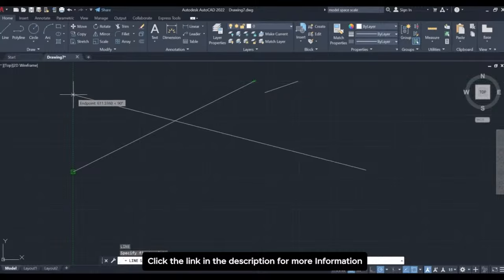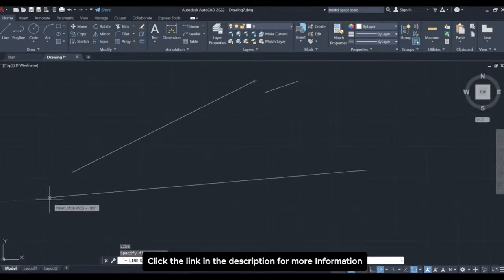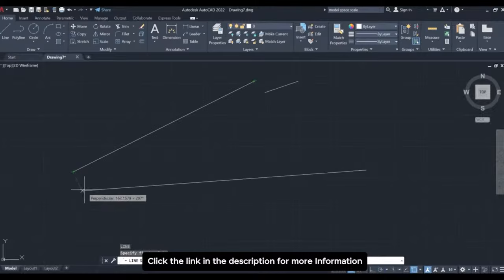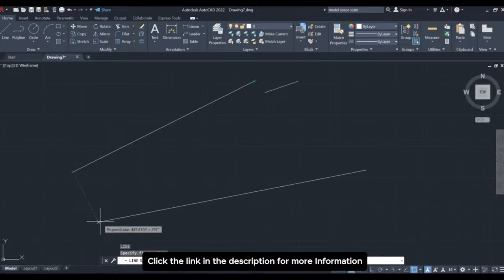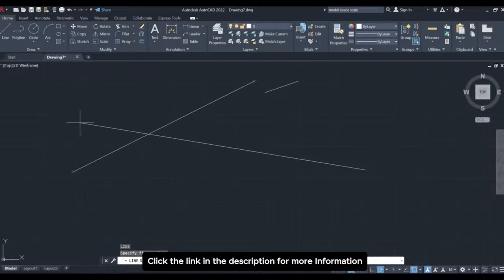All right. If you ever want to turn off this green line, which helps you track across the object snap, just press F11 and you'll no longer be able to track across it. The reason you're seeing these is because F10 is on. That's for your polar angles as well, right? It will, however, give you representations for the perpendicular angles to that, but you won't get any object snaps in the other angles that you would wish for. All right. You can't track them in the other angles.